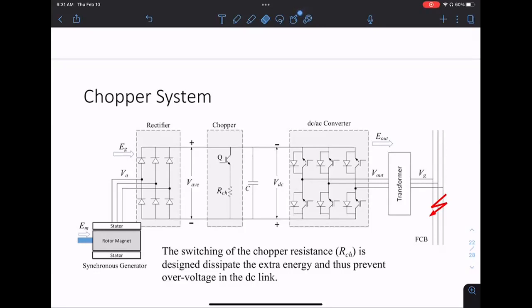In this kind of application, we're not that constrained by space. They just show you a huge capacitor. If you are doing microelectronics or embedded, you're space constrained. A lot of the art of designing circuits is how do you not use a huge capacitor? How do you control everything so you don't have to use one? We typically don't have that issue. We're not that space constrained, so you can put in a large capacitor and just make sure you protect it so nothing happens to it. Okay, so here we'll look at some equations, at how much power you have to dump through this resistor for things to work.